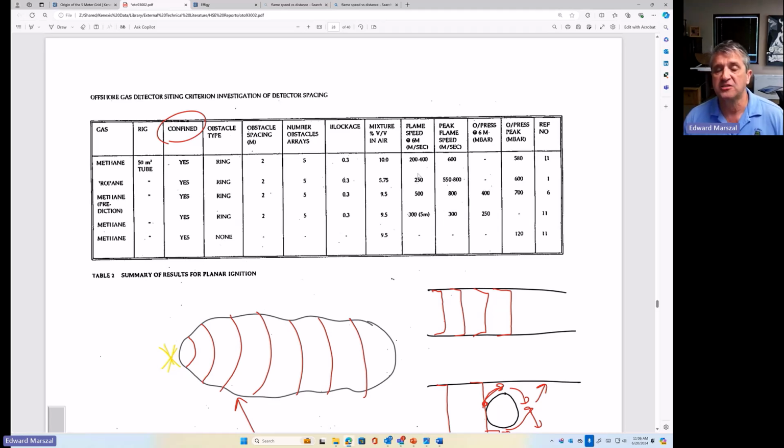And using scenario coverage with dispersion models is going to give you a much more accurate assessment. But no, the critical gas cloud size has absolutely nothing to do with dispersion modeling, weather conditions, wind speeds. None of that is factored when you're doing geographic coverage.